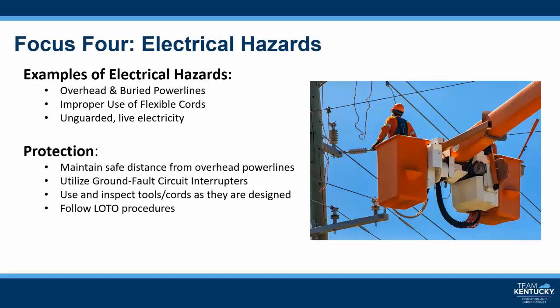However, burns and falls from elevations are also hazards that workers are exposed to while working in the vicinity of high voltage power lines. Workers may not realize that cranes are not the only equipment that reaches overhead power lines. Working on a ladder, using or moving scaffolding, or working in a man basket suspended under or near power lines also poses the risk of electrocution.